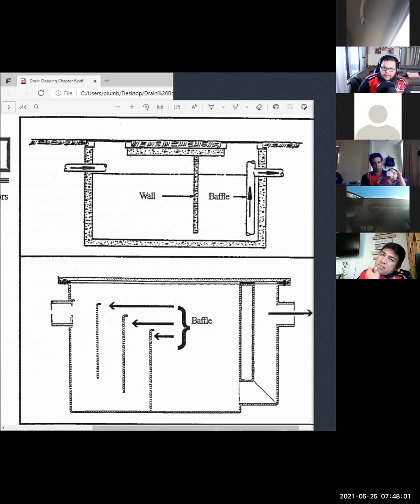One other thing also is that when we're snaking drains in a commercial kitchen like this, it's always good to know where the grease trap is, because now you know what kind of distance you're dealing with on your snake. If your grease trap is 40 feet away from the last fixture, you're not going to send your snake 100 feet down that drain, because you'll end up in that grease trap. So it's always good to figure out your surroundings when jumping into commercial kitchens.